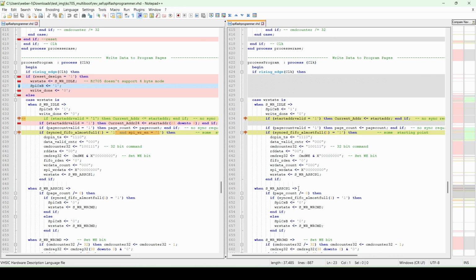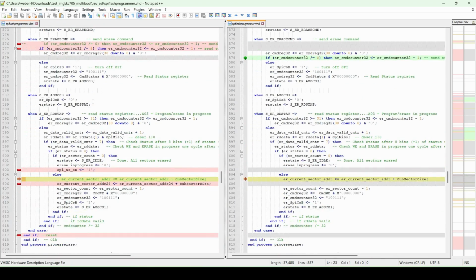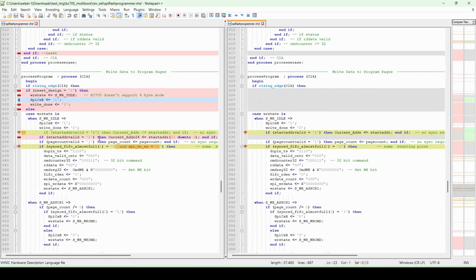When we created this demo, we experienced several times that the warm boot sector was all erased by 0 and broke the boards. So we put some improvement code here to gate the SPI write. Only when this successful erase sector is finished can we let the SPI write continue.